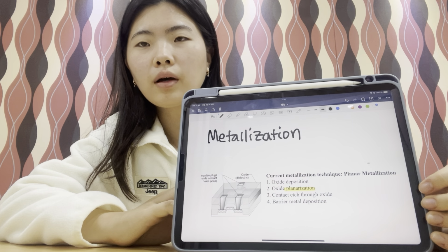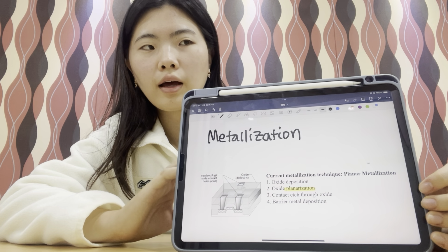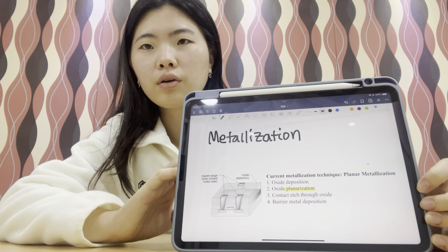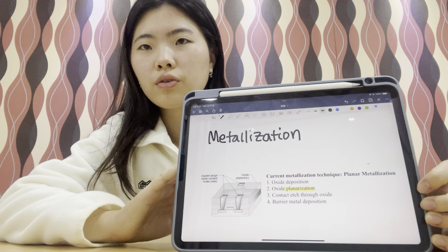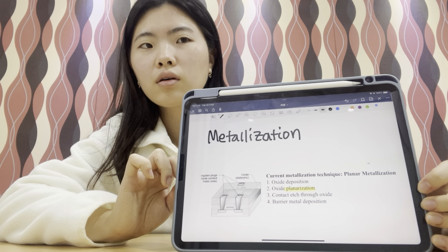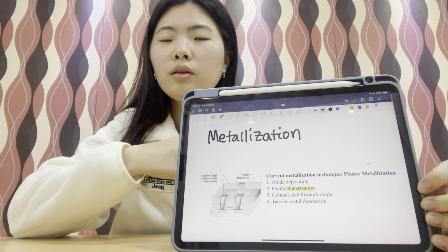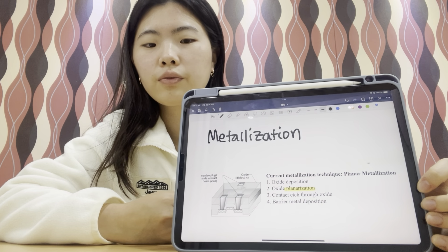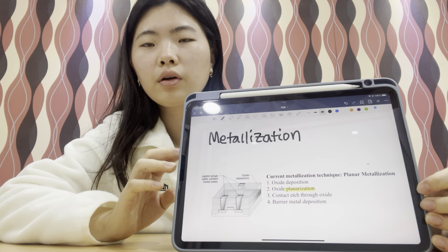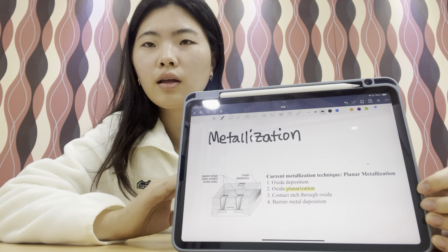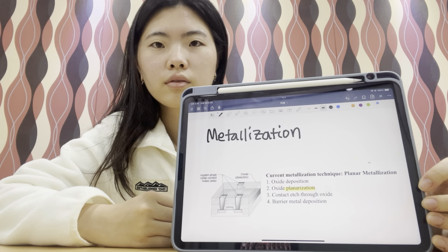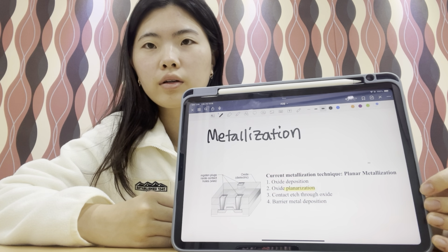Metal sometimes doesn't have a good adhesion to the interlayer deposition. It means when we do develop or lift off to this material, contact material or something else, everything can be deleted after we do that work.